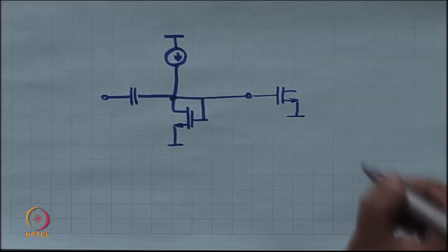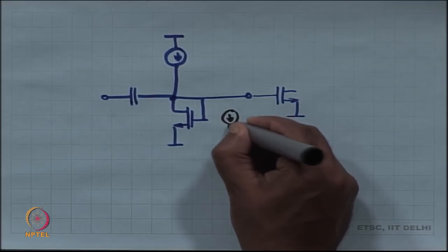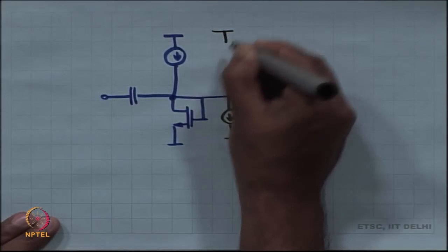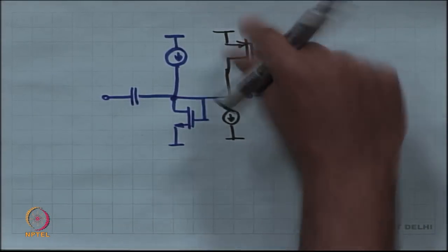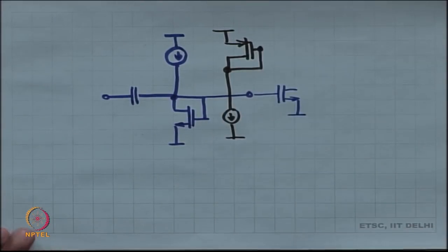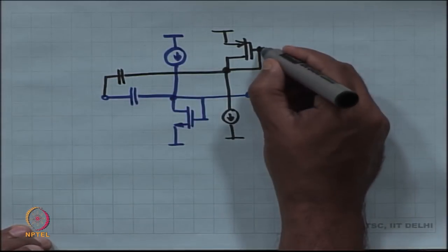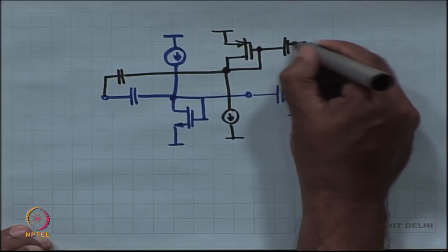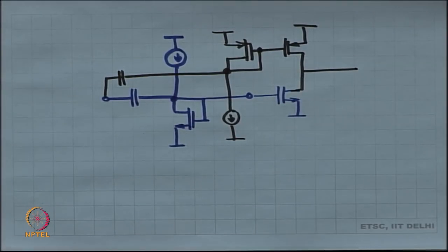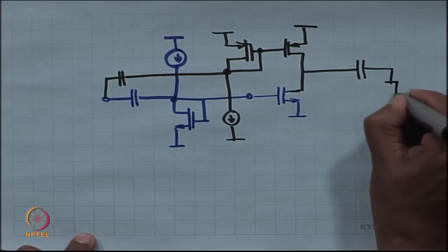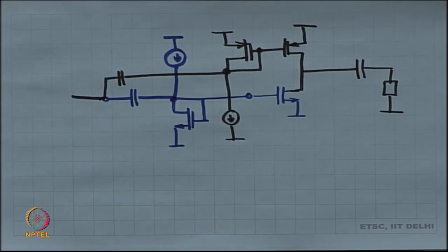And likewise, a weak current, if you pull it through a large PMOS, you get a VT drop over here, and you can couple in your signal, and that goes to your input PMOS, and then you organize them as push pull, decouple the load, and there you are. Okay. So, these things can be done.